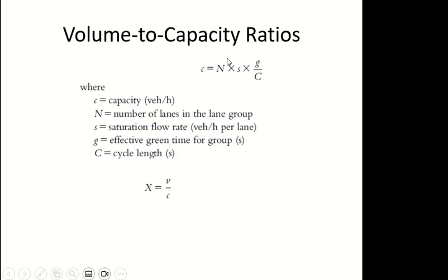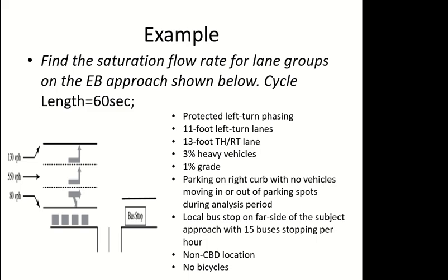So what do we mean by critical lane group? In the previous one, we had 2 lane groups, right? This one and then this one. So you need to see which one is more critical for the signal design. If you are allowing all these lanes to go in the same phase, then you cannot design for this one and this one and this one, all of them together.